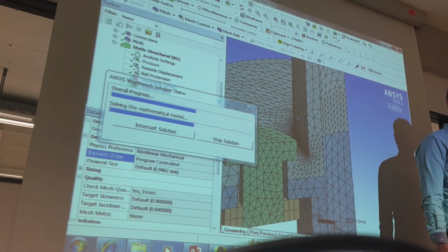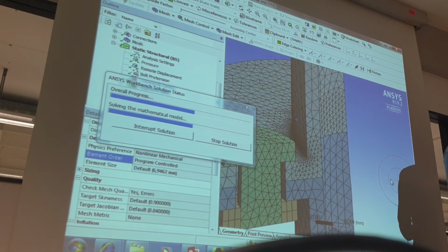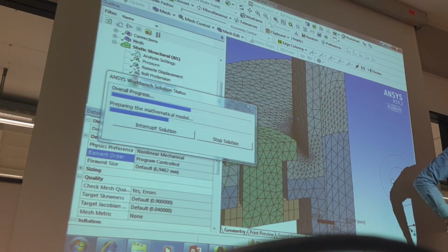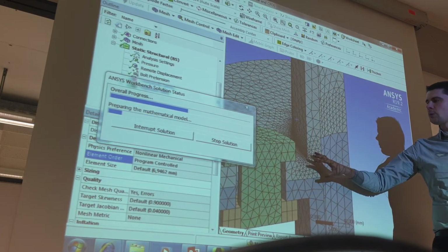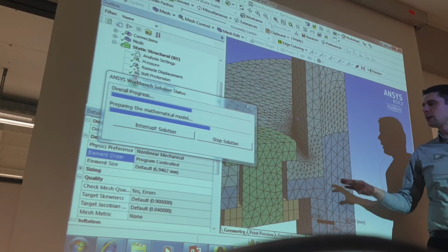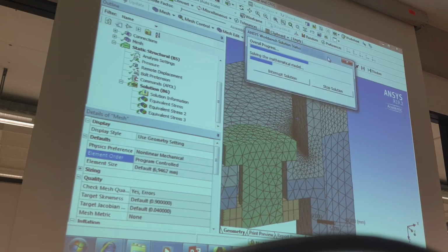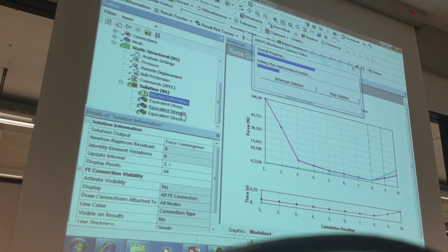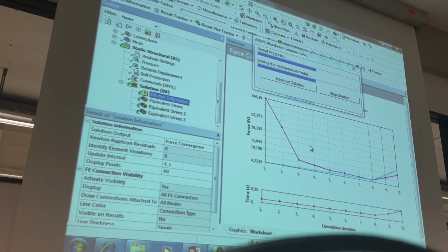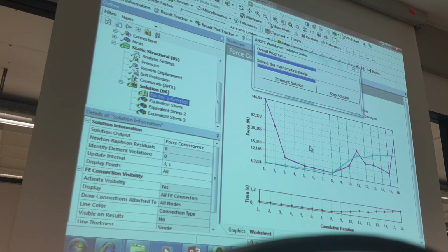Did you understand the idea? Yes, we do everything that's possible to save time. So, for example, program control says quadratic, but we say no, please, everything we don't need is linear. Okay, and now we are waiting for this part. It's interesting whether it will be quick or not. And then we change this, and I show you how we can say exactly here linear, here quadratic, and then we answer the last important question: does it break our part or not.